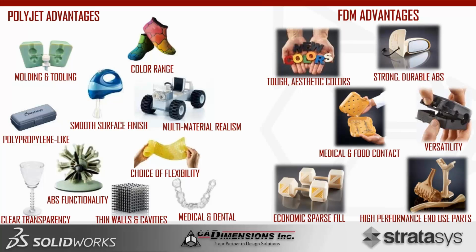But to summarize that, essentially, if you're looking for strength and durability with 3D printed parts, FDM is really where you want to go. The technologies boast much stronger materials, again going back to the ULTEM 9085 and ULTEM 1010, that can resist up to 10,000, 15,000, even more than that, psi resistance.